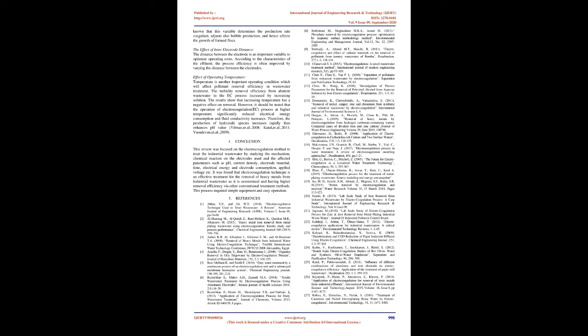Effect of electrolyte, NaCl, concentration. It is important to investigate the effect of electrolyte concentration since actual wastewater usually contains a certain amount of salts. As the electrolyte concentration increased, the removal efficiency increased due to the increment of the electrical conductivity, reaching the maximum value. However, with the further increase in NaCl concentration, the removal efficiency decreased. Prasanna et al. 2005. Sodium chloride is usually employed to increase the conductivity of the water or wastewater to be treated.